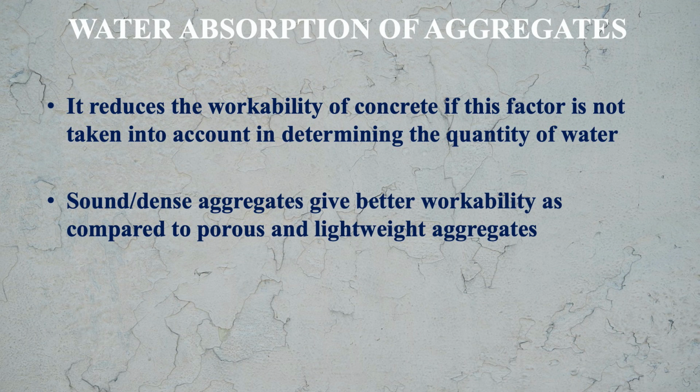Means if by chance such aggregate is being used for making the concrete, then we have to take into account how much amount of water will be absorbed by the aggregate, and we have to make up for this absorbed water. Means we have to add more water for making the concrete so that workability is not affected. The sound and the dense aggregate give better workability as compared to porous and lightweight aggregates. So this is the effect of water absorption of aggregates.